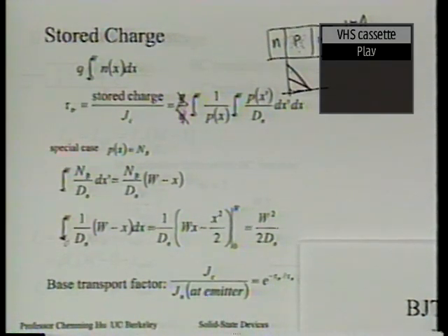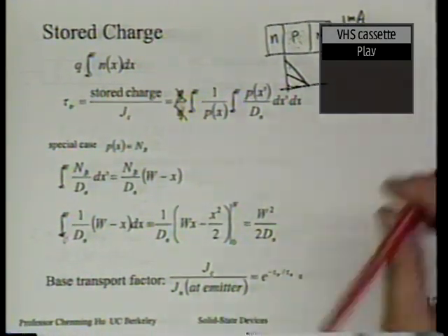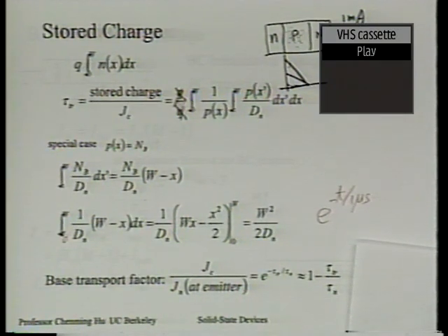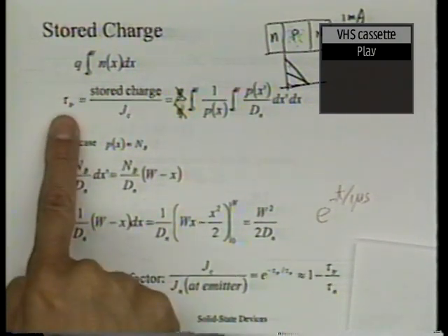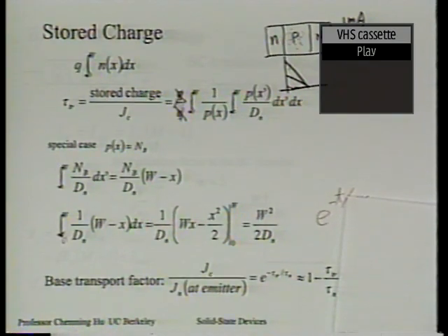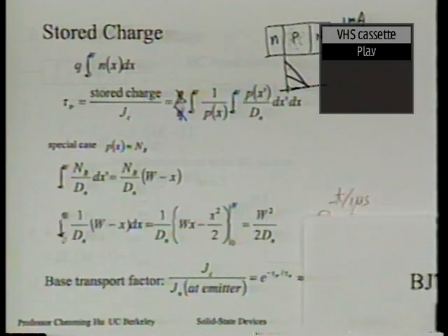It's a stochastic process, right? That is, immediately some start to recombine, and many of them will live long before 1 microsecond, right? So exactly mathematically, how does this 1 microsecond factor into the life of these 100 electrons? At any time t, this much will remain: exponential minus t over 1 microsecond, right? That's the random process. If you know they're random and they have a mean lifetime of 1 microsecond, that's the meaning of it. Is that right? The fraction that remains is exponential minus t over 1 microsecond. Since we know it takes tau tr to transit through the base, and that is what I meant as the link to arbitrary dopant, so if you know the arbitrary doping profile, you know the transit time is tau tr, then what fraction can survive that transit?